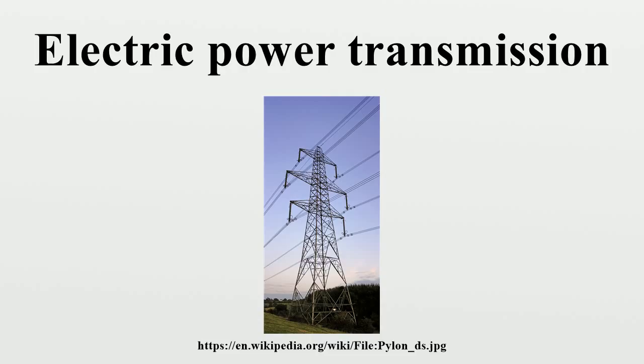A very first operative AC line was put into service in 1885 in Via dei Cerchi, Rome, Italy, for public lighting. It was powered by two Siemens and Halske alternators rated 30 horsepower, 2 kV at 120 Hz and used 200 series-connected Gaulard 2 kV/20 V step-down transformers provided with a closed magnetic circuit, one for each lamp.